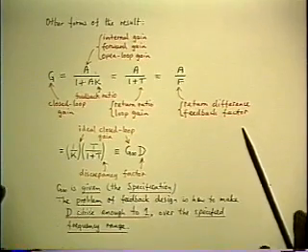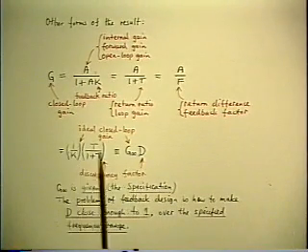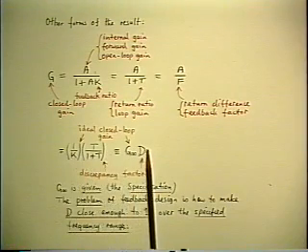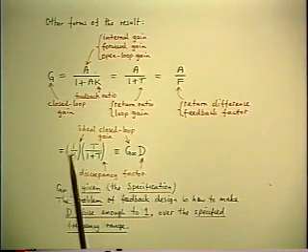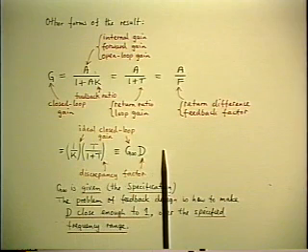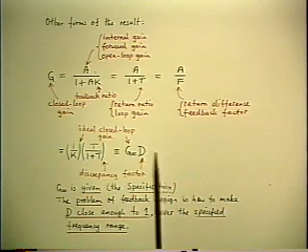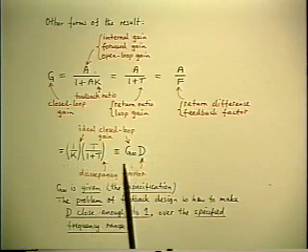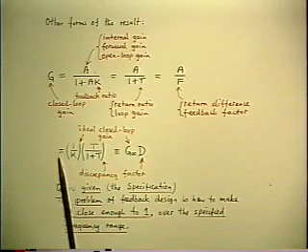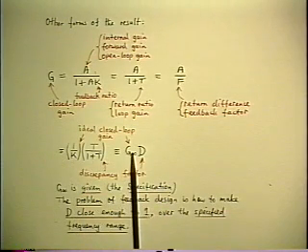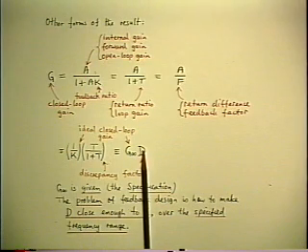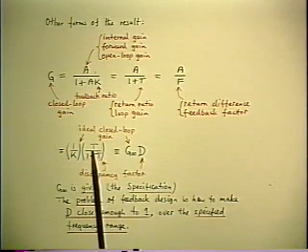So I'm proposing now to deal with the whole subject of analysis and design of feedback amplifiers using this representation. In other words, we've substituted the quantities that are of importance in the result into the original expression. And the important quantities are the specification, G infinity, and how close you're going to get to it, which in turn is directly related to the loop gain.